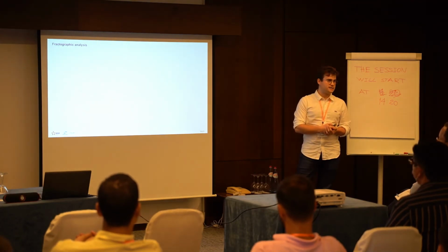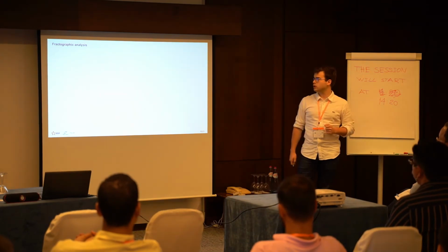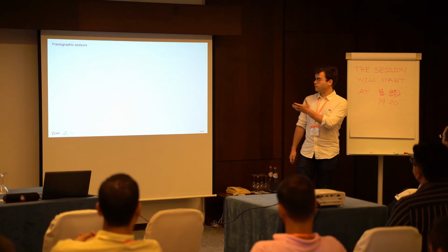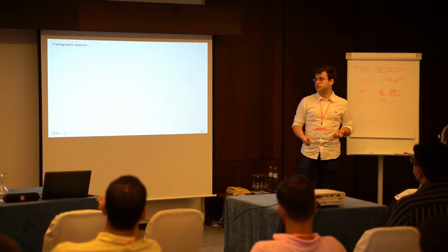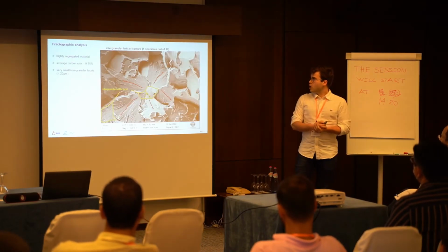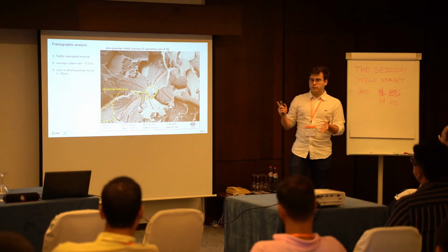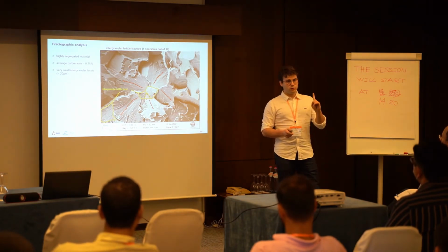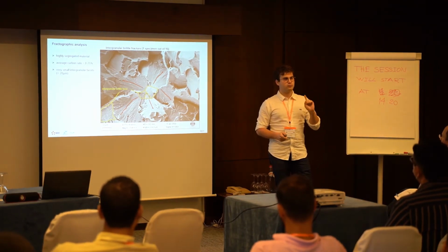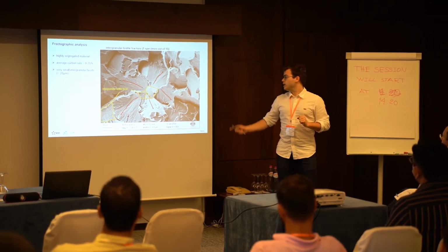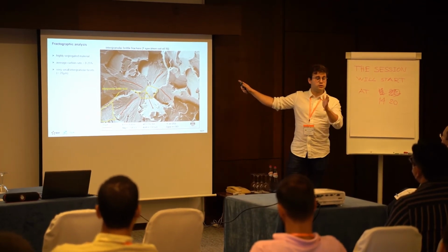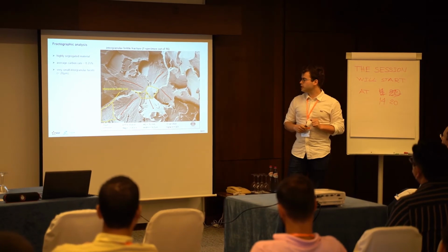Fractographic analyses were also performed to evaluate the fracture mechanisms of this kind of highly segregated material. Among the 16 samples that were analyzed, only one presents an intergranular brittle mechanism. The fracture surface of this sample is shown here.